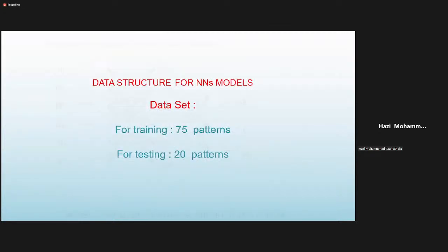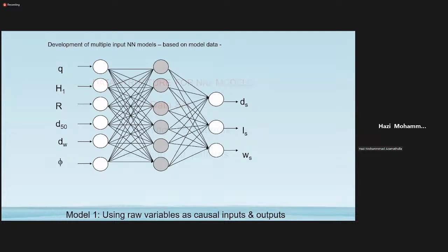Okay, next please. This one is for the model. Yes, now you can see here. You all remember dimensional analysis, right? Here on the left-hand side are raw variables only. I did not do anything. First time using raw variables, the actual inputs and outputs. On the left-hand side you can see discharge, intensity, head, bucket radius, bed material, depth of tailwater level, and so on. And the output, continuously you need for plunge pool depth of scour, location of scour, width of scour. Then it works like a continuous model. That's the beauty of this neural network model. Okay, next please.